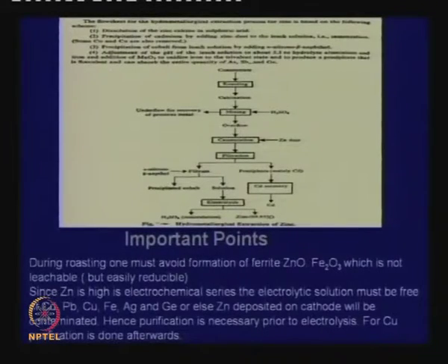That is a pyrometallurgical extraction, but today hydrometallurgical extraction has become much more important, where we take zinc into solution after roasting and calcination. The solution goes through very elaborate purification process, because unless the solution is very pure, it will not be possible to electrolyze zinc, because we have to depend on activation over potential to ensure that hydrogen potential becomes more than the zinc potential.